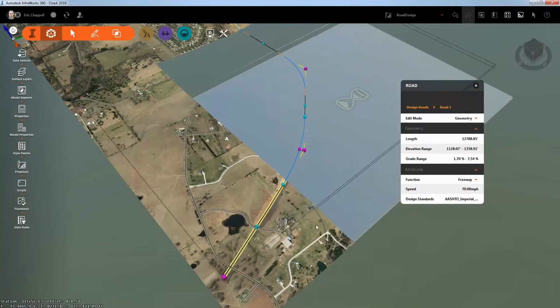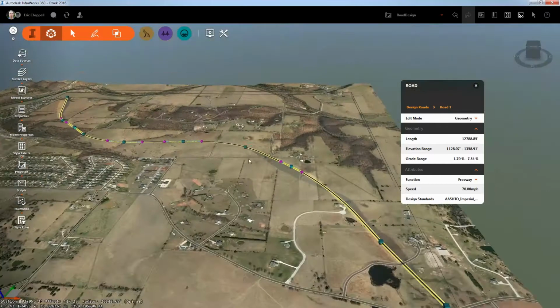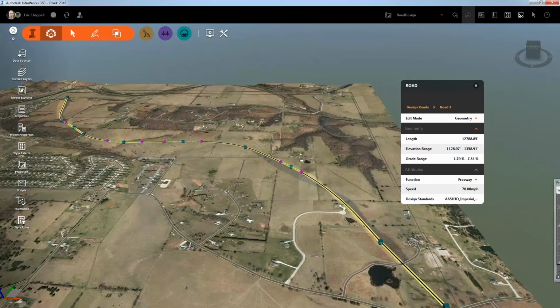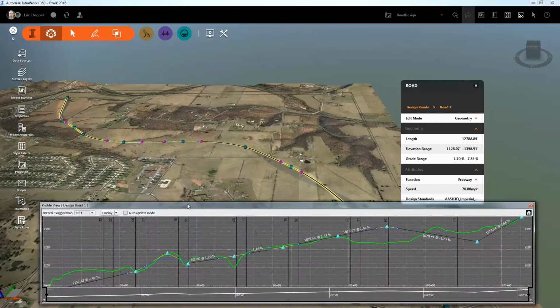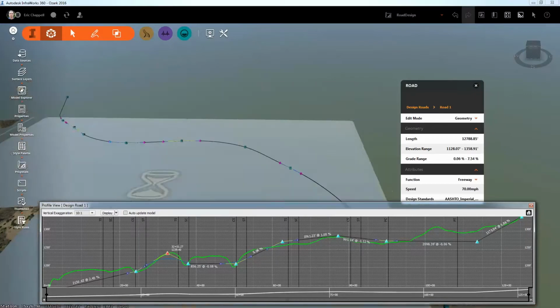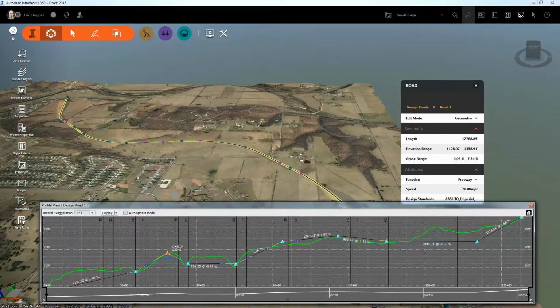And then what I was talking about earlier with the profile view, if I switch into profile view and I make some changes, you'll see the changes previewed with the gizmos and the ghost lines in the model, but they won't actually be committed to the model until I move my cursor. I don't have to click or anything. I just simply move my cursor into the model area. You can see the blue donut pop up, and then the model is prompted to update.